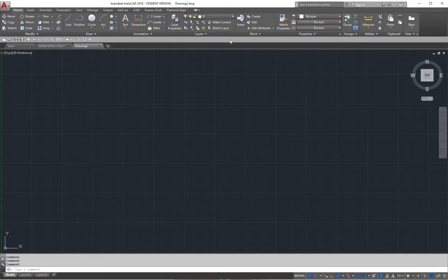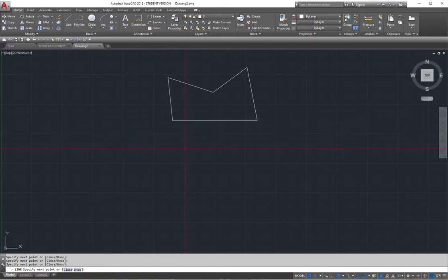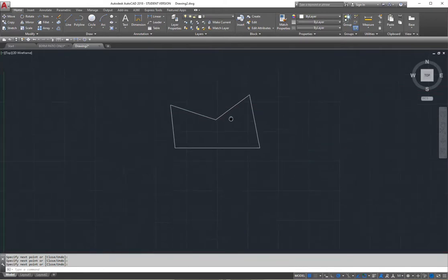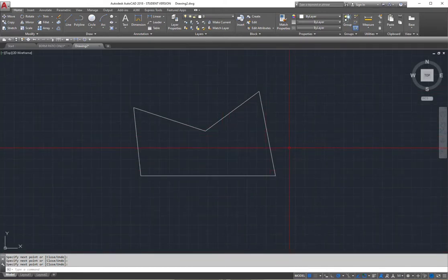The first and most important thing is going to be right here on our ribbon, on our Home tab, at the middle. There's something called Layers. As of right now, you have been creating some drawings and just start drawing something. If I go and draw any given line, click any starting point, my lines start appearing right here. We have a random number of lines going in random directions, and they're white, and that's it.